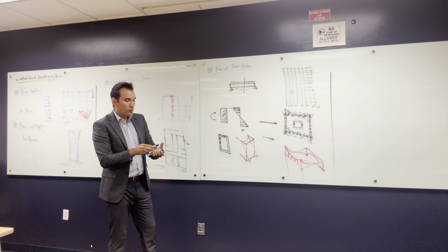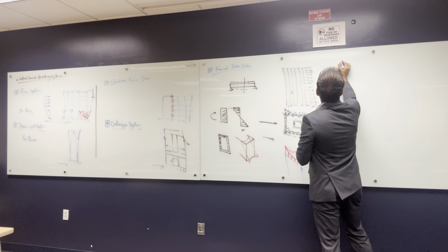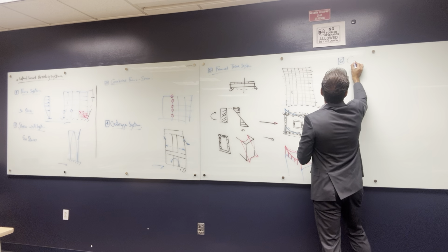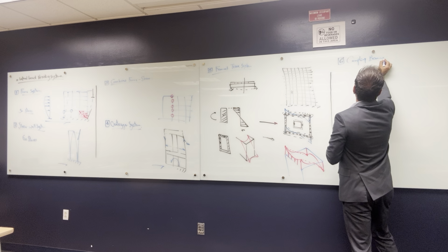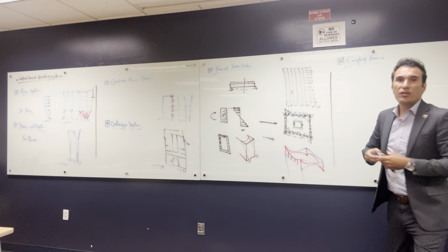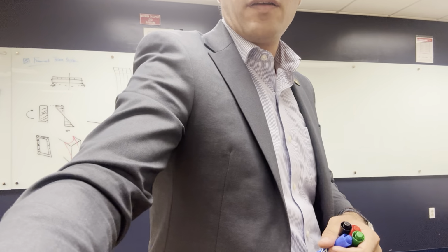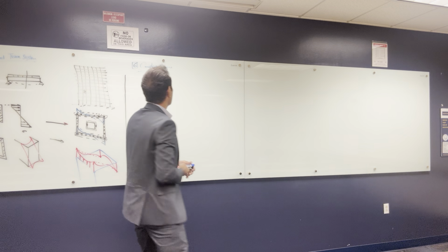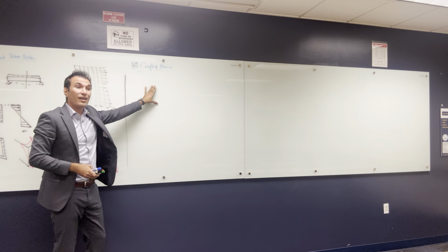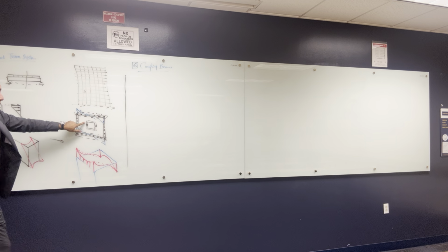That will take us to an interesting topic about the coupling beam. You guys heard about coupling beams before? Actually, there are sections in the standards about coupling beams, how to design them and how to reinforce them, so that these two walls, this one and this one, act as one.